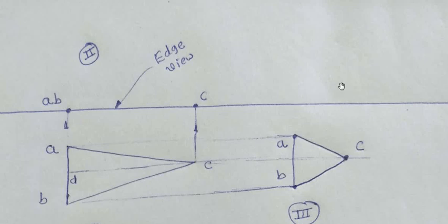And we will draw projector from C, and on this projector somewhere point C would be lying, and the distance between this probable location of C and this AB, which is in the HRP, this length would be equal to length of this edge view, because in our usual procedure we do not change this length of edge view, we simply give it inclination. So in reverse manner, we will first plot AB here, projector from C, and the exact location of C would be taken by the compass with distance of edge view in the previous front view.